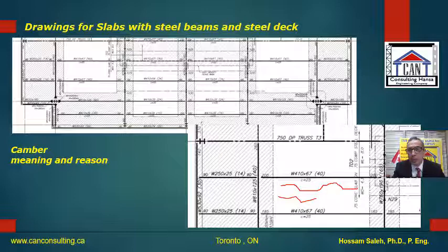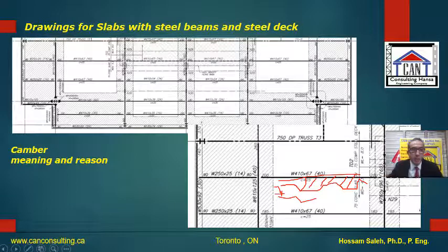and that's the sheet itself, and this depth here is 75 millimeter, and then at the top of this steel deck you have the concrete topping. So this concrete is 75 millimeter, measured from here to here. That will be 75 millimeter on 75 steel deck. Okay, so that's the direction of the steel deck, and here is the topping of the concrete.